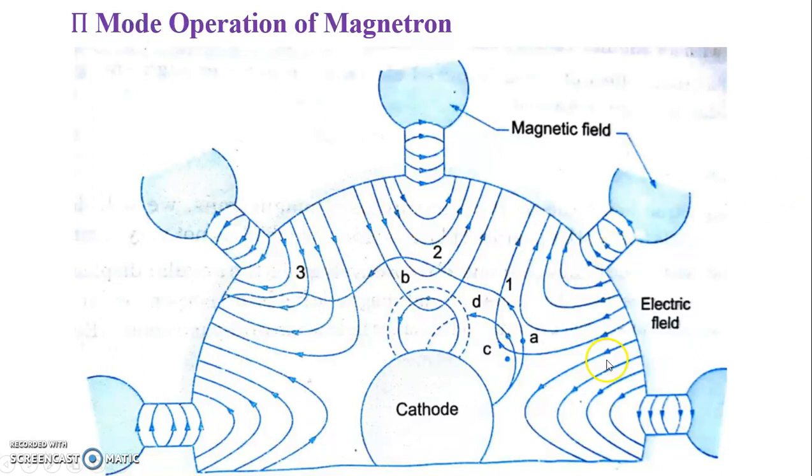The electron A is seen to be slowed down in the presence of oscillations, thus transferring energy to the oscillations during its longer journey from cathode to anode. Such electrons which participate in transferring energy to the RF field are called favored electrons and are responsible for the bunching effect.